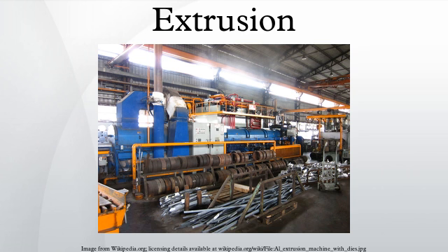The disadvantages are: impurities and defects on the surface of the billet affect the surface of the extrusion. These defects ruin the piece if it needs to be anodized, or the aesthetics are important. In order to get around this, the billets may be wire brushed, machined or chemically cleaned before being used. This process isn't as versatile as direct extrusions because the cross-sectional area is limited by the maximum size of the stem.